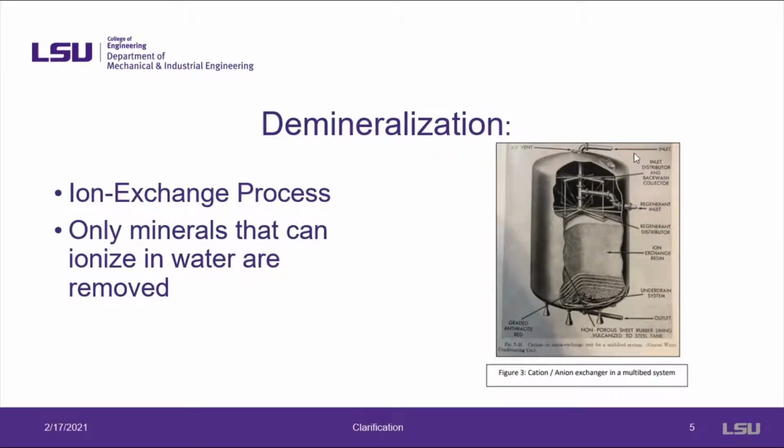The first step is for the water from the clarifier to enter through the top of the exchange unit, where it then comes into contact with a graded anthracite bed. Anthracite is used due to its ability to bind with minerals in the water. Anthracite is another word for coal. Over time, the exchange unit will become full of minerals. For this reason, a cleaning process is employed.